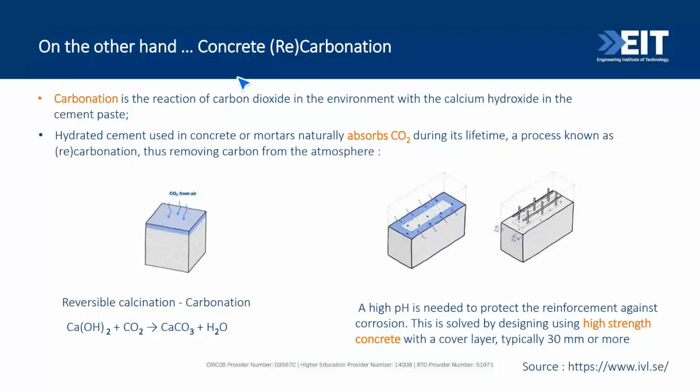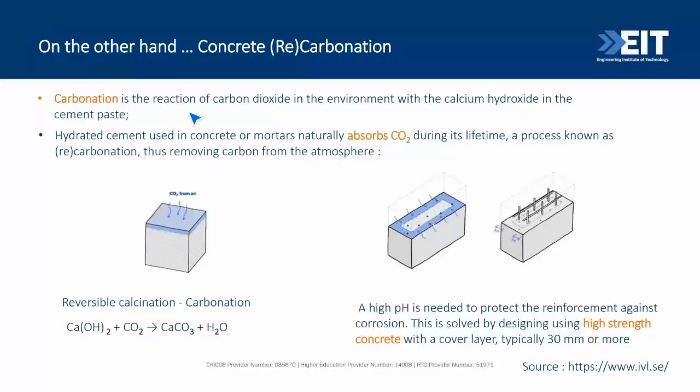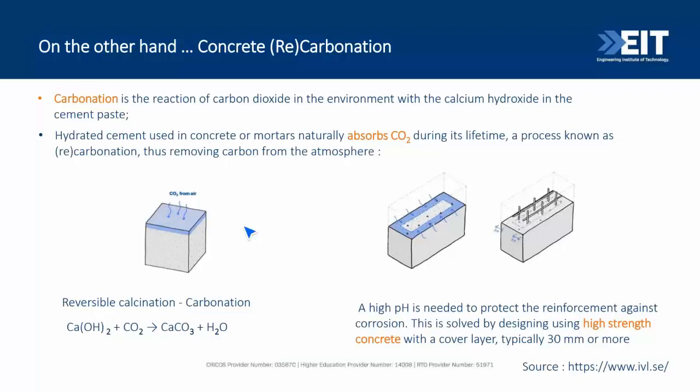On the other hand, concrete can absorb carbon dioxide, right? It's not new. Carbonation is the reaction of carbon dioxide available in the environment, and it will react with the calcium hydroxide in the cement paste, right? It's not new. But here I'm going to pause and ask you another question. Just please have a look at this slide. Reflect on the decarbonation of concrete.